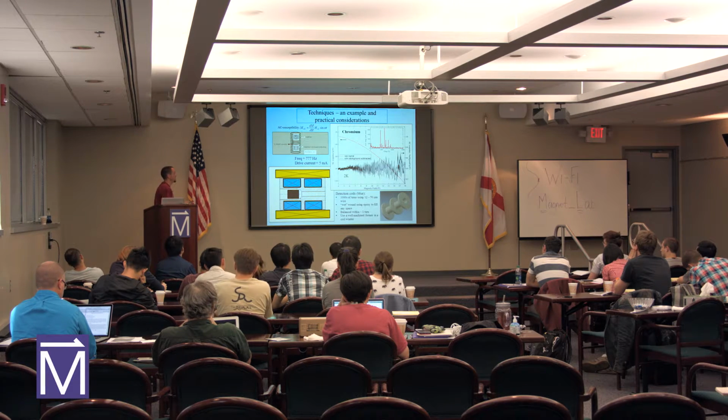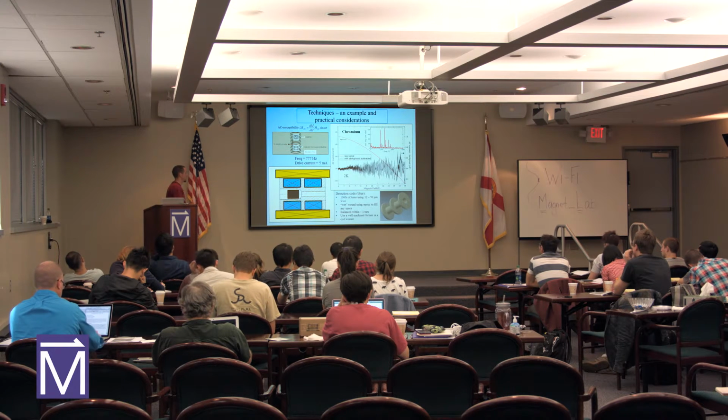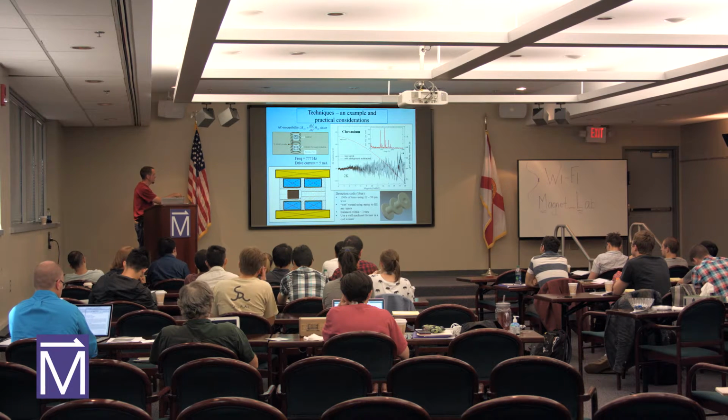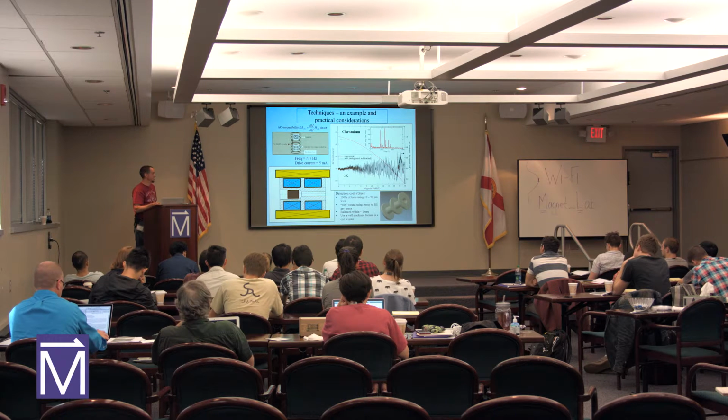Okay, a little bit more about AC coils. This is kind of a nuts and bolts explanation of how you would actually build one of these things. So if your advisor or supervisor gives you the task of making this, that's how much of your life you're going to waste working with really fine wire. This rectangle out here represents the drive coil. This can fit inside a pressure cell sometimes, so the entire width of this assembly might be as little as 3 or 4 millimeters.